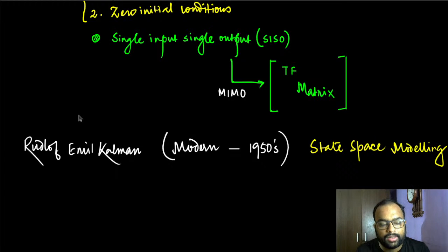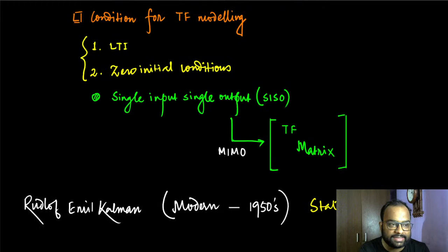So the idea is that even a very complicated system that cannot be handled at all by the transfer function approach, the state space modeling technique can work. If these conditions are satisfied so that we have a transfer function, then it is even better, because then we would definitely have the state space model as well. The idea is very simple. If we can construct a transfer function model, then that definitely also has a state space model. But it is not the other way around.